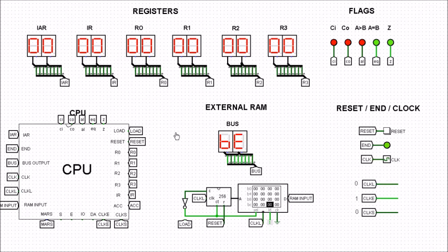Okay, so that's almost loaded. When it gets to FF, that's it finished loading. So that's at FF, and you can see it's put in the value 3 and then the value 4. That's it moving these values into memory. It then takes one of them out of memory, so it takes value 3 out, and then it'll add value 4 onto it to get an answer of 7. So you can stop the clock there, and that's it finished. It's got the answer 7 sitting in R0, and the end command here is the CF.